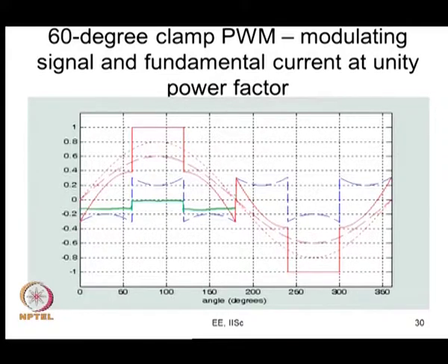Now the current has a 0 crossing, and therefore the error voltage also changes sign, and the error voltage is positive here. Again in this interval the R phase is clamped to the negative bus, therefore the error voltage is 0, and once again the error voltage is positive like this. And how much is this error voltage? As before, it is VDC TD upon 2TS. This is what it is.